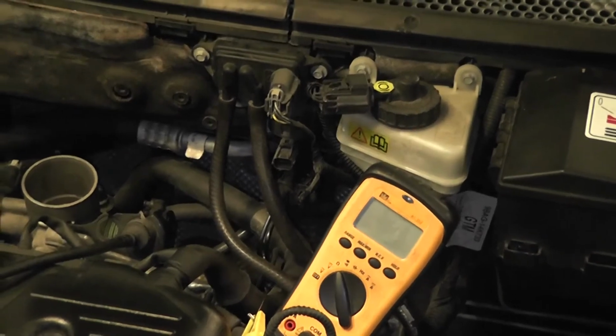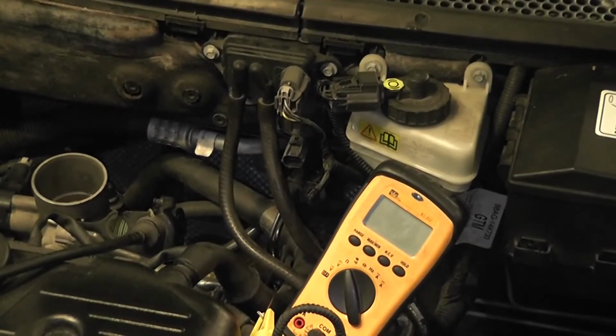And it's a very simple test from this point, knowing that the left side of the connector is my control wire based on our voltage readings. The right side is the feed. I'm going to take that same test light to battery positive, and we're going to touch on the control wire, and then we're going to take the scan tool in a bidirectional mode and command this EVR solenoid to turn on. So that's going to be our next step.